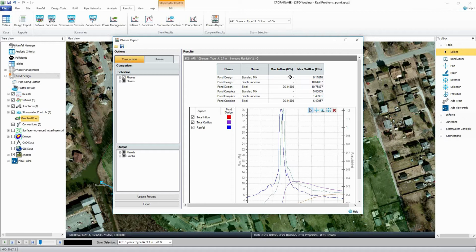This one is the channel's discharge. We didn't get much flow at all out of the channel, a ton of flow out of that pipe. And you'll see the resultant flow out of the pond system is about 10, almost 11 CFS. If we begin to restrict flow through that pipe and divert it into that channel, we'll see that the channel gets about 5 CFS, and we really reduce the pipe system down to maybe more appropriate levels. Ultimately, we're restricting this flow down to about 6.5 CFS.